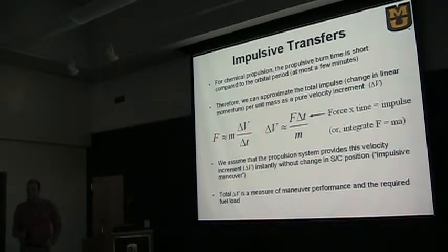That is delta V. That's my equation I could use to estimate how much velocity was imparted on the spacecraft instantaneously. So you assume that because the force is so high, that velocity change happens almost instantaneously. You fire a rocket, that rocket only fires for a few seconds, and then the velocity changes by a large amount to make the orbit transfer happen.